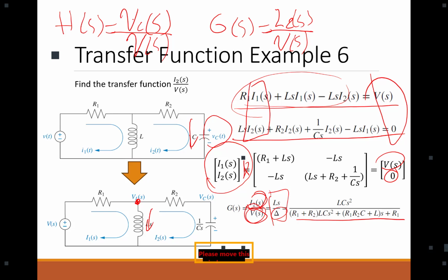The height of that surge is going to be significantly higher than the nominal voltage that you're working with. The actual capacitor, especially the electrolytic capacitor, has a certain tolerance. If you pass the tolerance, it will explode. So you need to know what you're doing.